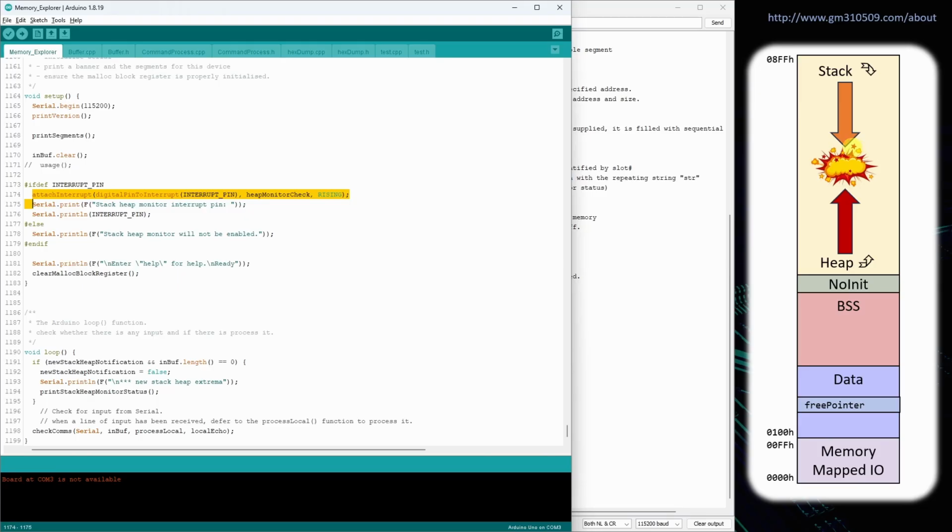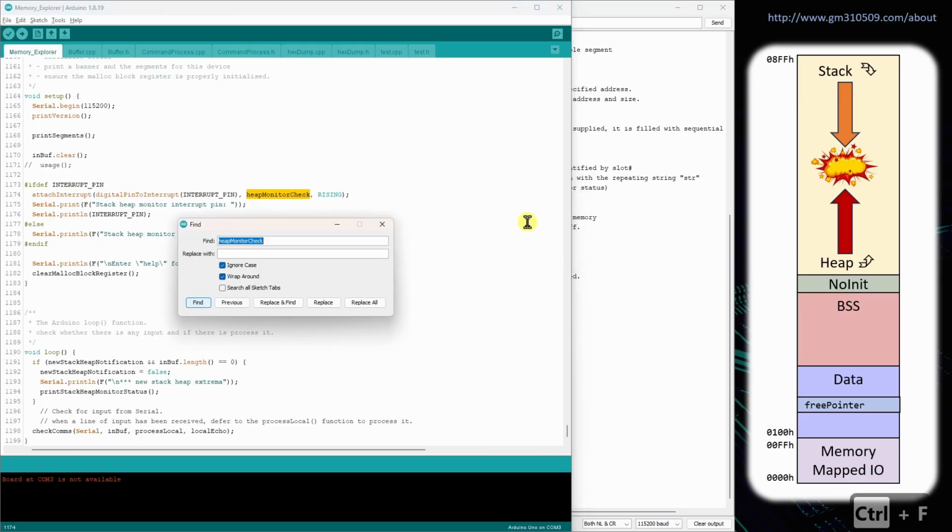So that's a good way of sort of seeing. And also it will fire independently of what's going on. It'll fire when it's inside the system functions or whatever. And so you have the most reliable chance of seeing the bottom of the stack. The drawback to that is that if it goes down quickly and comes back up, you might not see that peak. So that's just the trade-off. But using an ISR is sort of essential. And so that's the name of the function that we're going to run when we fire the interrupt.